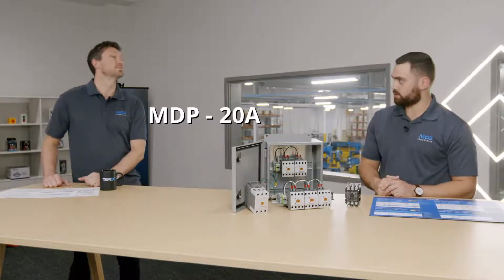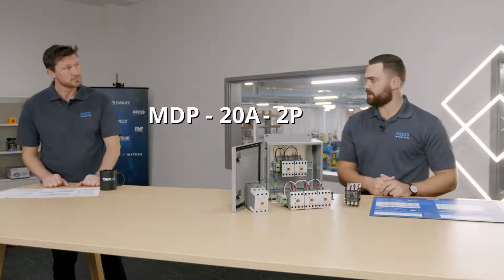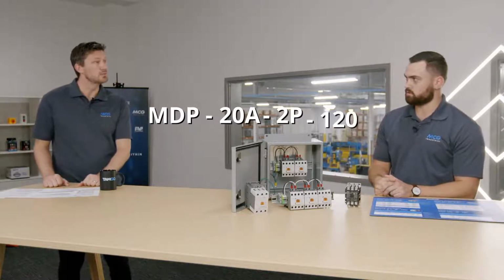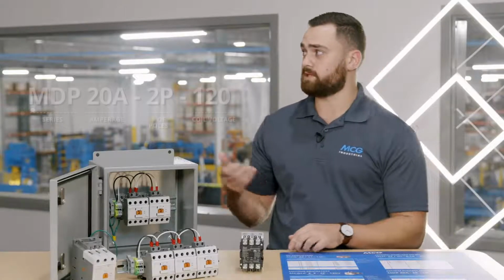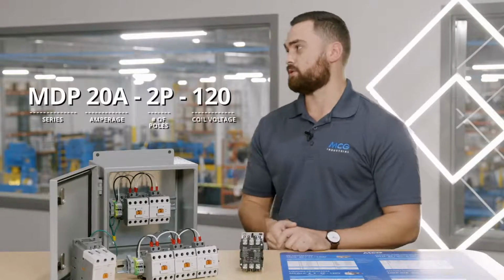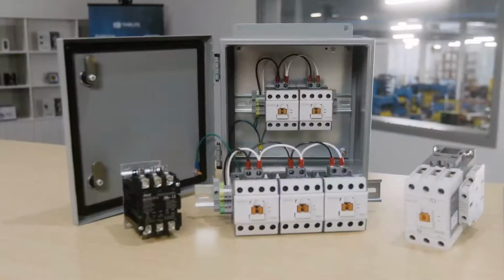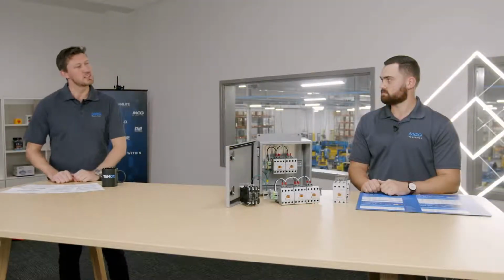20 amp. 20 amp, okay, and what's the number of poles you need for that contactor? 2 poles on this one. 2 poles, all right, and lastly, the coil voltage. 120 volt. 120 volt, perfect. So Anthony, your part number following our matrix is going to be MDP 20A-2P-120. Awesome, that was simple. Exactly. So I've got my definite purpose contactor, but what other contactors do you have?